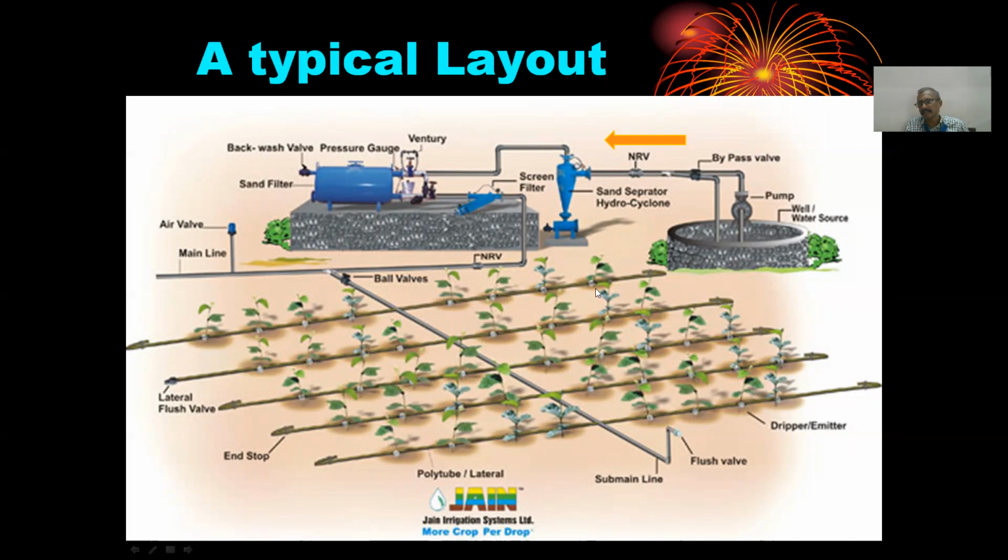The drippers are touching the ground. So when the air gets into the pipes through the drippers, it will take a lot of soil particles along with it.